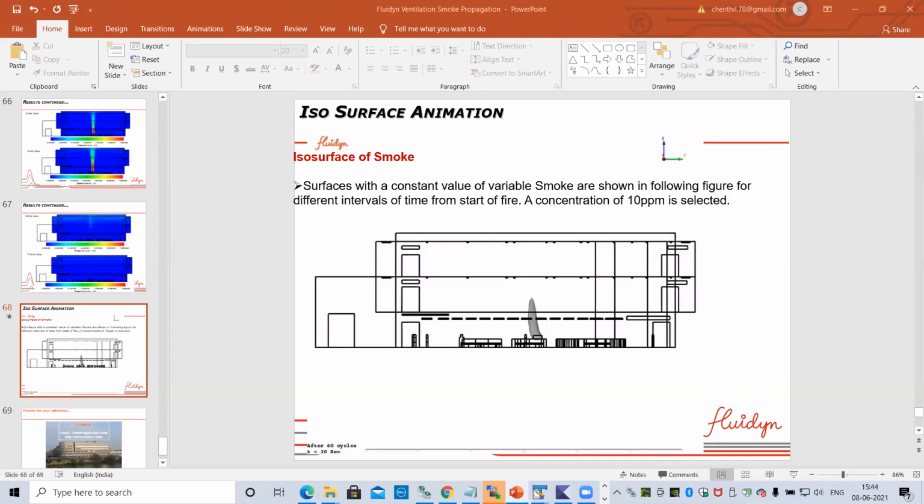Hi, this is Aramurthy here. Smoke is basically a collection of particles, so it is not non-Newtonian. You have to model them as particles. Depending on size, they behave differently: very small particles are controlled by Brownian motion, and large particles behave like individual particles which settle quickly. You cannot model that with a non-Newtonian fluid. You have to use a two-phase model or an aerosol model, which is also available in Ventsim. You can define the smoke as aerosol and model how it moves and disperses.